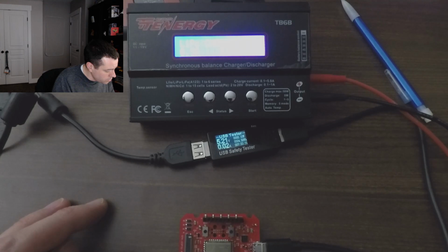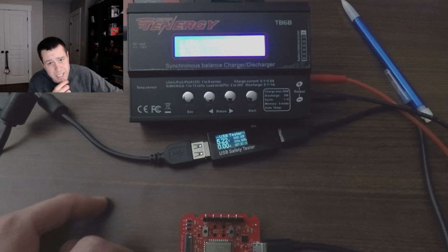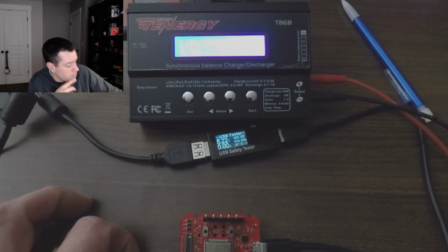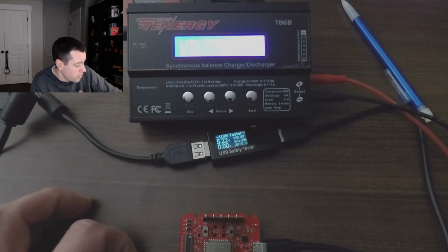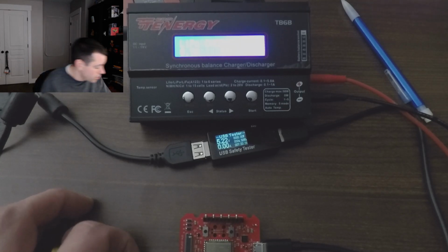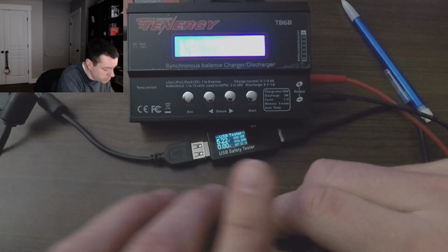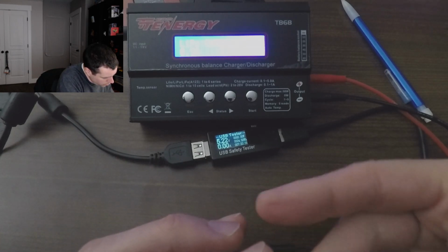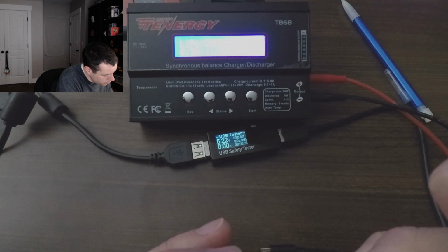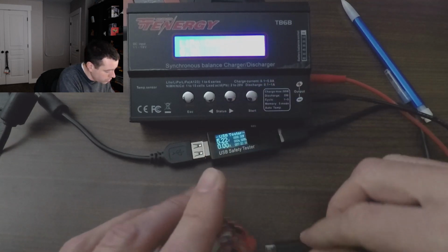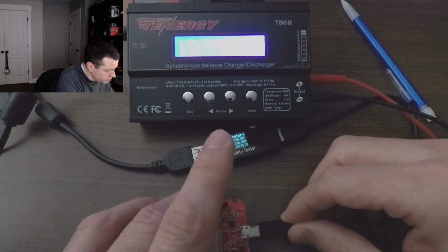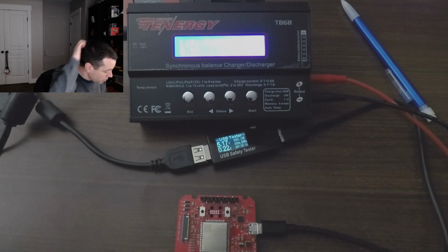And then it'll drop down to 0. So I guess I would have expected to see 182 and then drop down to 180? But regardless, when it was asleep, it was juicing the battery with 180 milliamps. Let's just do it one more time. Make sure we're doing this right. So that looks good. Looking real good. Here we go, 220. This is what I was seeing. Now it's down to 180.